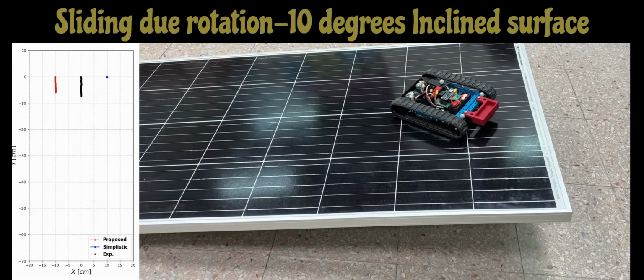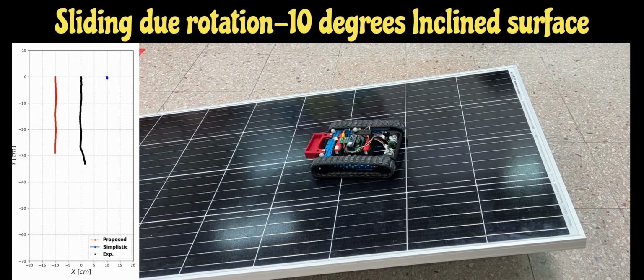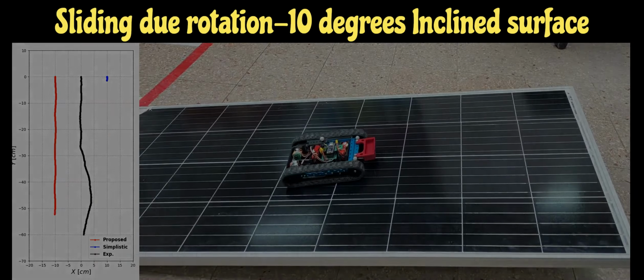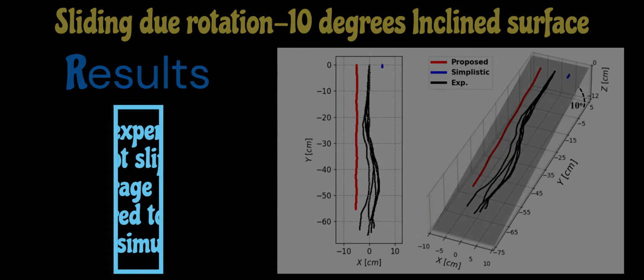In this experiment, we compared our robot model to experiments where the robot tries to make a pure rotation on a 10-degree incline during 10 seconds. In the experiments, the robot slipped by an average of 61.8 centimeters compared to 56 centimeters in the simulation.